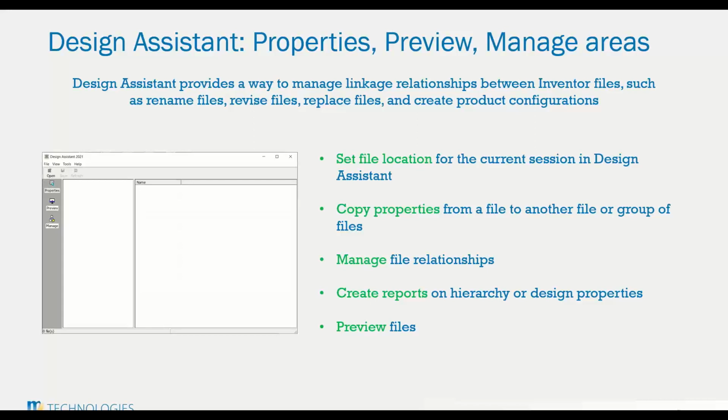So again, talk a little bit more about the three areas. The Design Assistant always provides a way of managing the linkage relationship between the Inventor files. Again, if you are looking to rename files or revise files and replace files, create product configurations, this is a good tool to use. Again, setting the file location for the current session in the Design Assistant is done through your set project, whatever your project is set. Your default workspace will be set within that project file.